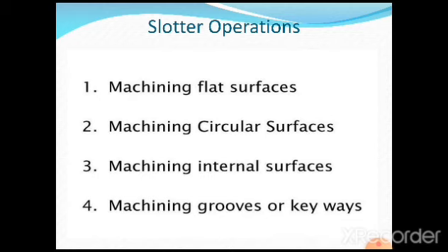All these operations can be carried out very quickly, provided all the adjustments are made in connection with the stroke length and the working of the mechanism. One important point that all of you need to understand here is that the cutting stroke is always slower than the return stroke. That is how the mechanism is going to function, and all this facility or motion is provided with the help of those mechanisms which we have discussed in the presentations.